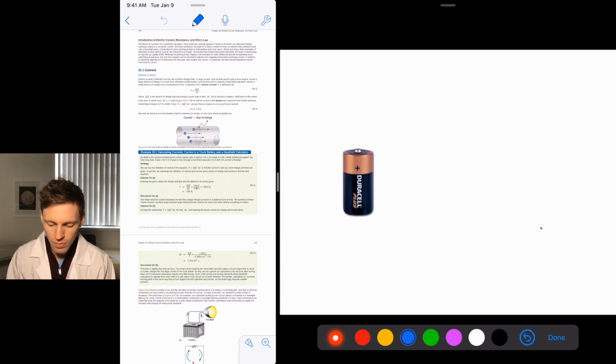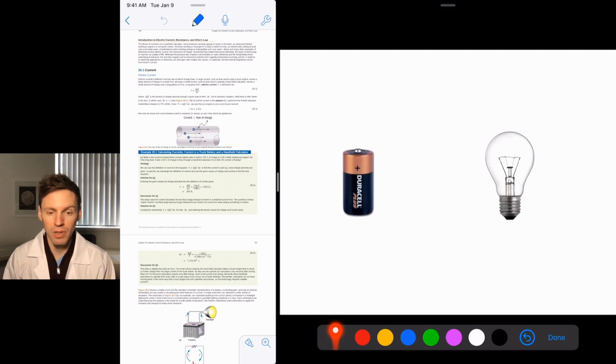All right, so let's say you've got a battery with a positive terminal and a negative terminal, and you want to light a light bulb up. This light bulb has a metal screw part here, and then there's this black insulator, and at the bottom there's a silver dot, which is the other connection. Current needs to be hooked to this part so it can flow up through the filament and then back out, isolated, out the bottom to the other side.